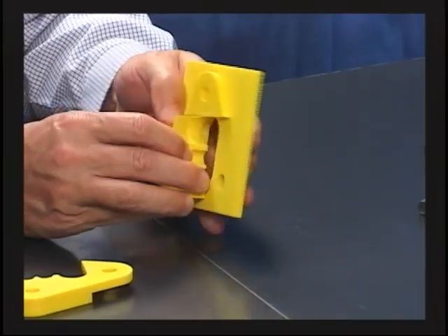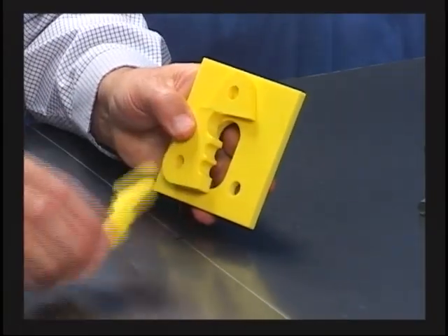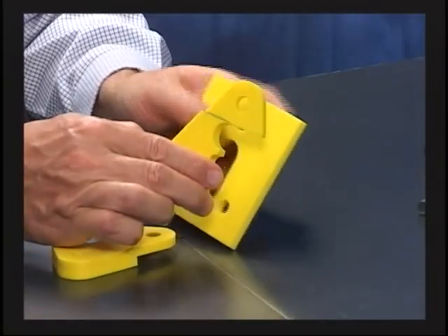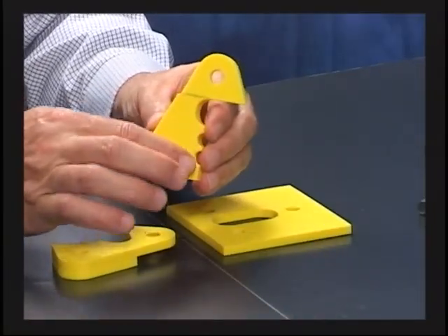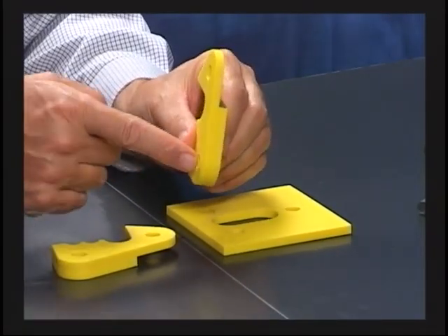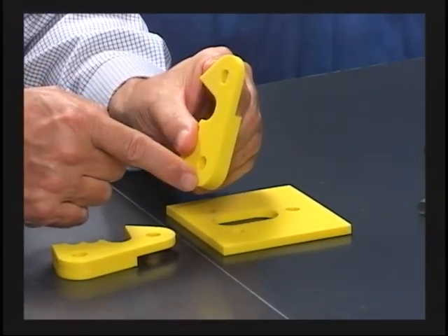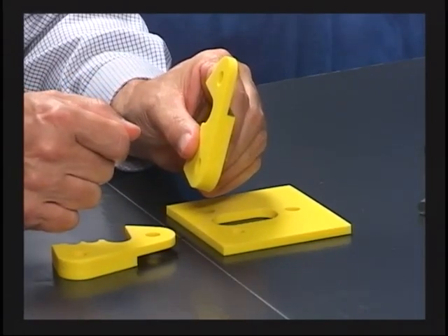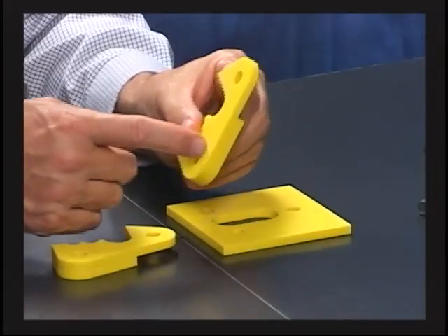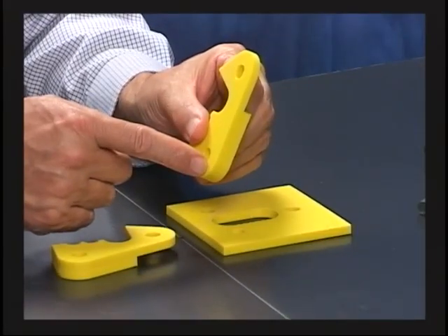Now you might say, well, that part mounts up, but this one, when it goes on, mounts on the other side. Why didn't you pick the front face? Well, I guess I could have picked the front face just as well as the back face, but you notice I saw the back face being longer, so I selected that as my primary datum. If I have a choice between a long one and a short one and I can't decide, I would just go for the long one. So that was my primary datum.